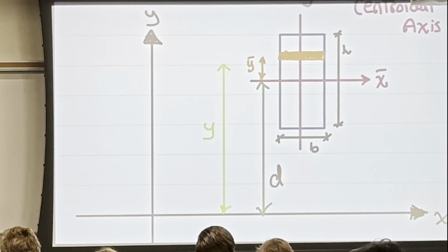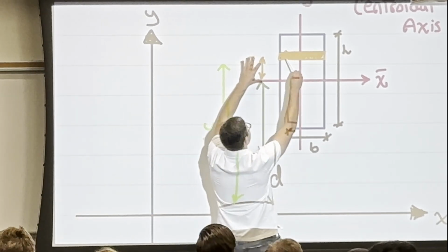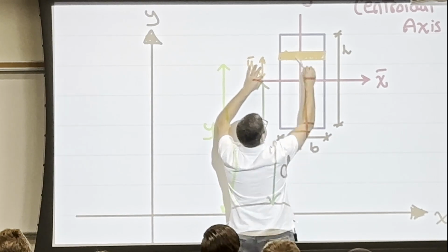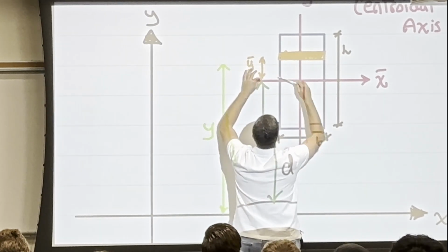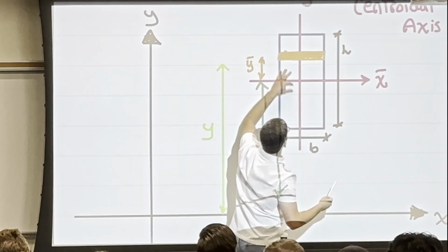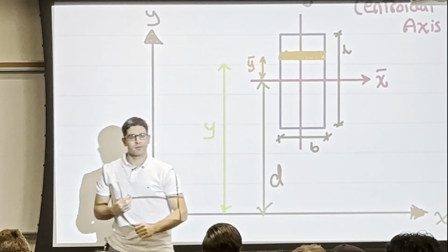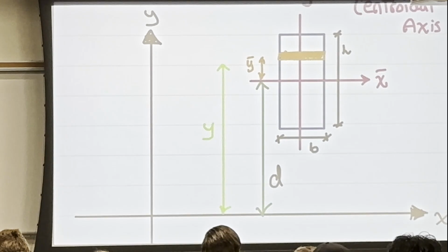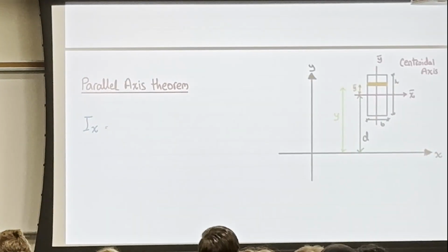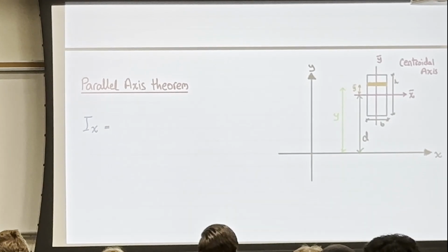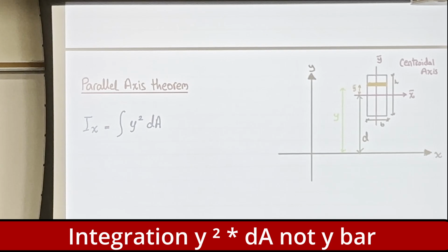Okay? So this y bar is going to increase in the positive x bar direction, and also increase in the negative x bar direction. So this strip is going to go up and down within that area. Again, the equation for Ix is equal to the integration of y squared dA, and now y here is...